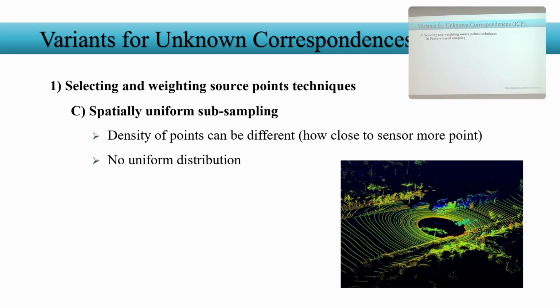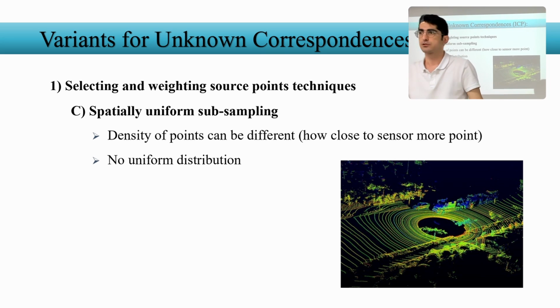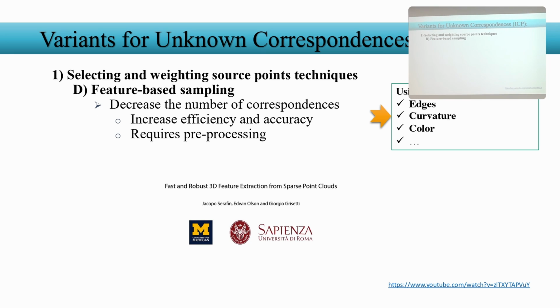On the other hand, you should consider that here you have fewer point clouds, and here you have more, and your robot moves from there to here. Then from the same scenario you have more, so the scale is also different. You see this one in the point cloud from far. When you come here, it is the same, but everything is changed. So that's called uniform subsampling, and you need to be aware that it exists. But ICP usually does well if you tune the parameters well.